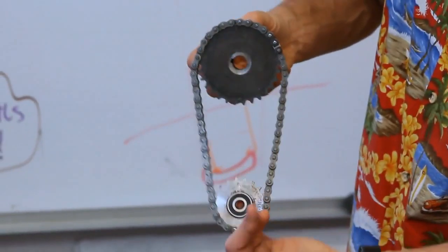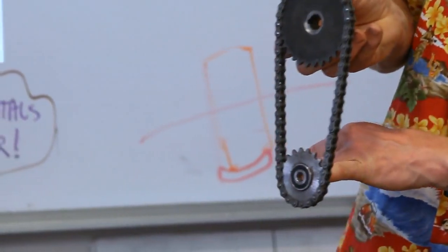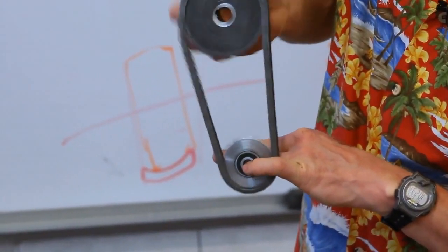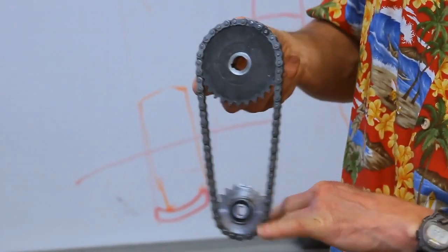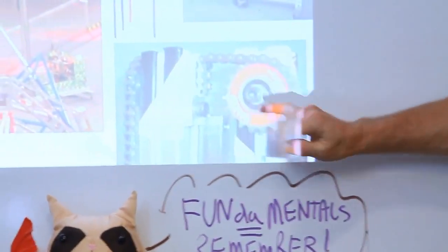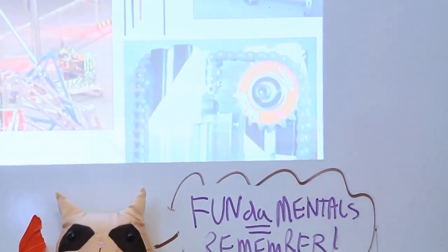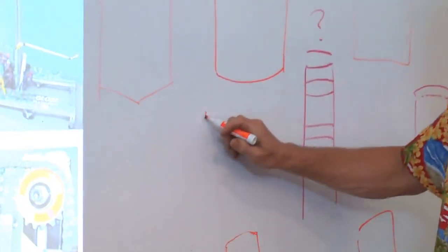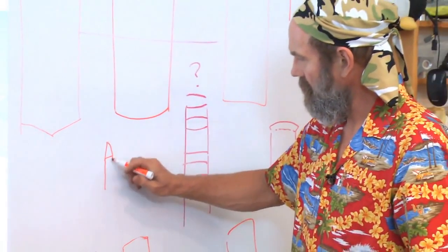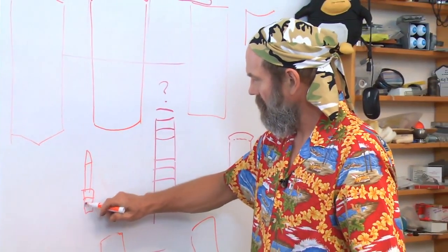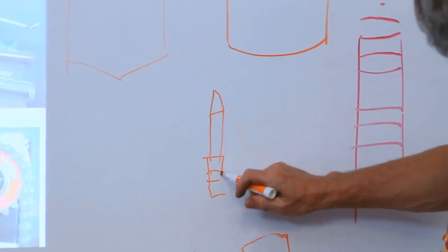And notice here when I hold the center bearing fixed, I can then have that motion. Whereas this guy here, at the top of the mast, simple bolt through, is able to take the load, because in that case, when you have an idler sprocket, here's the bearing. And it's very thin.